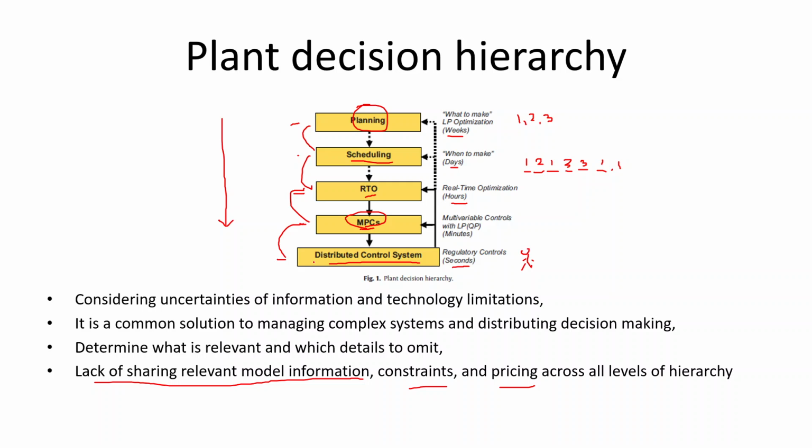But for the MPC and RTO, is it a similar kind of system that can decide by itself according to our constraints? Like with DCS, we put a set point, so it always goes to the set point. But for MPC and RTO, do they work like that, or do you put some constraint or set point that it has to follow? What I understand is that this RTO is more in steady state, and this one is in dynamic mode.